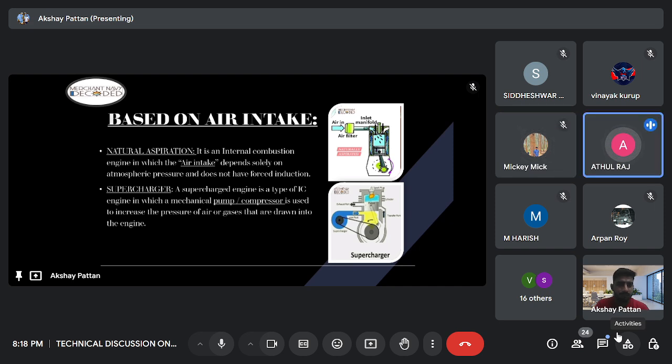Okay, but in the case of a turbocharger, it will take some time, till the engine starts, exhaust gas develops, then pressure develops. That time is called turbocharger delay. So there are disadvantages and advantages for both. And on ships we use turbochargers. There is no supercharger on ships. We use turbochargers for the main engine and also the auxiliary engine.